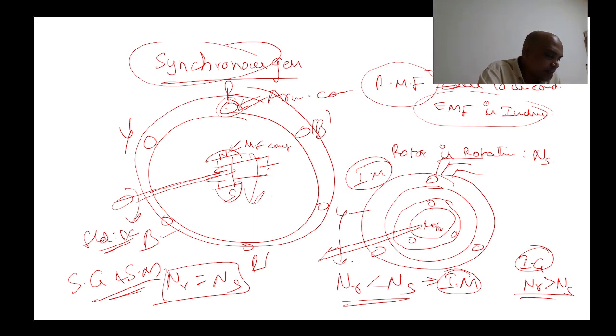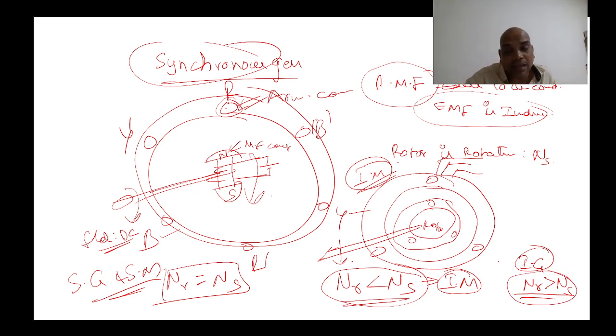Okay? But coming to induction machine. In induction motor, the rotor is rotating with less than the synchronous speed. In induction generator, the rotor is rotating with more than synchronous speed. Clear?